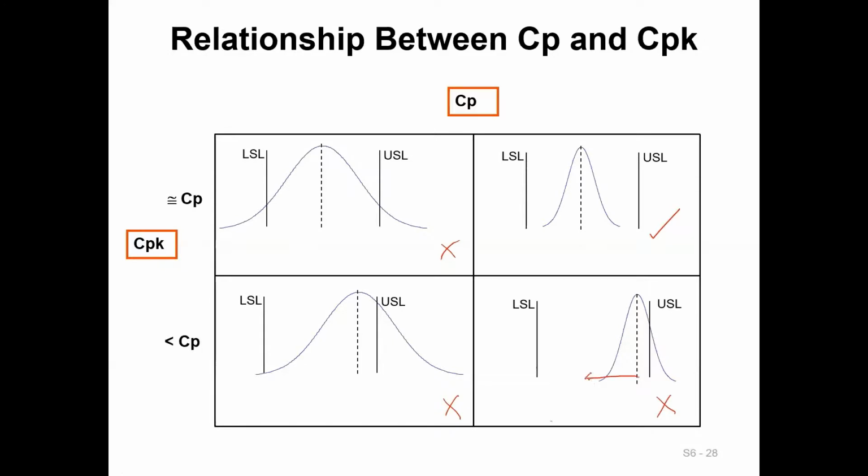For this case, the result is very straightforward: just shift the mean. The variation looks still alright within the spec limits. And for the first case, to improve the CP, the process capability here, the action required is to reduce the variations.